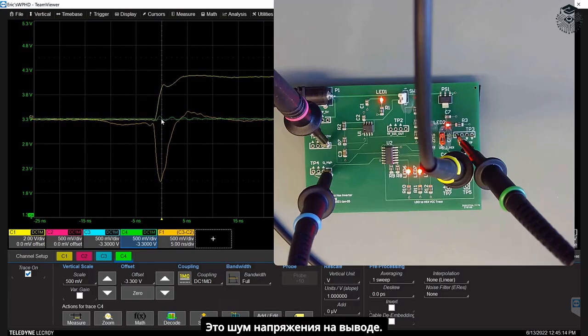This is the voltage noise on the die. This is the voltage noise on the board. Yeah, there's a little voltage noise on the board, coincident with the I/O switching, but it's a tiny amount compared to what we see on the die. This again is why it is so important to be able to measure the noise on the die, because that's where the action is. There's a built-in LC filter, a two-pole filter, between the noise generated on the die and the rest of the board because of the inductance of the lead getting to the capacitor and the capacitance of the decoupling capacitor. That's why we always want to be doing these sorts of measurements for rail compression. Now, let's return back to the slides.